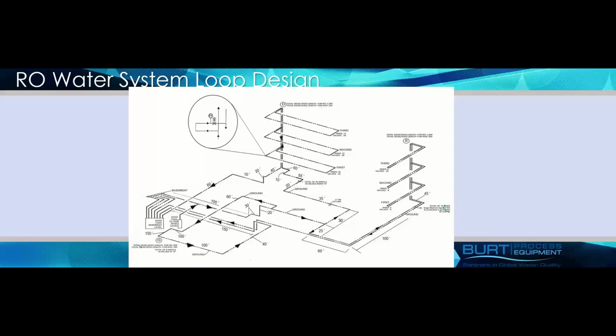And one of the questions that does come up, particularly in process and plumbing, is how do you really pick a flow rate for these systems? There are two factors to consider when looking at a high purity water loop. One is obviously what your use is, and you can apply things like diversity to that if you're looking at different fixtures or different processes, how much water you actually need. But you also need to build in an additional value into your system to allow you to maintain a turbulent flow, because you don't ever want to get laminar flow.